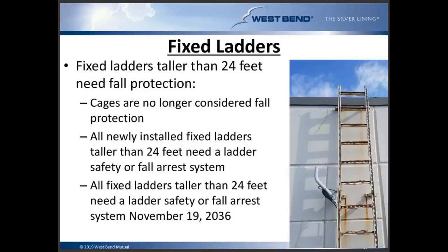and any newly installed fixed ladder, whether it be a brand new building that you're constructing, or maybe it's the replacement of an existing fixed ladder with a new one, if it's over 24 feet tall, it does need to have a ladder safety or fall arrest system in place, because the cages are no longer considered fall protection in OSHA's eyes. If you wait all the way to November 19th of 2036, and you haven't switched out your fixed ladder, at that point you will need to install a ladder safety or fall arrest system to those existing fixed ladders that may not have them.